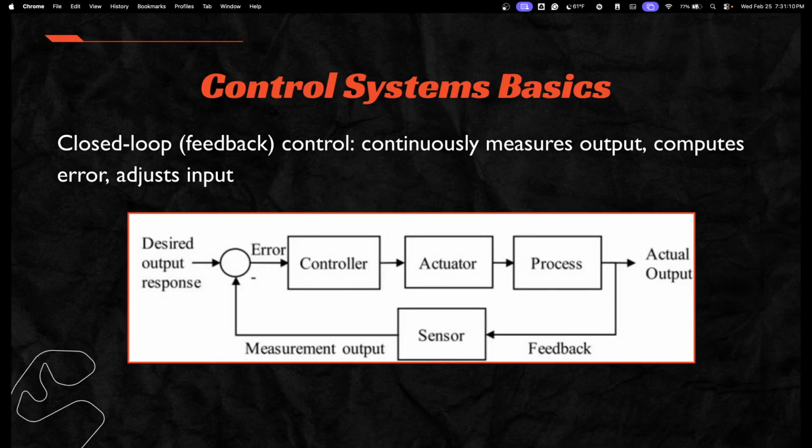So that's why you would need some form of closed loop, which is feedback control. Basically, after the vehicle tries to do 45 degrees, you have a feedback loop that tells the computer, actually the vehicle did not do 45, it did 47. And then the computer is like, oh, so there's an error of 2 degrees. And then based on what you want to do with that, your algorithm, based on that error, you change the next input, or the next command.